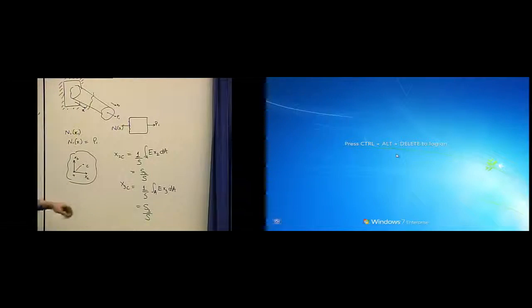But that is valid only at the centroid, so the centroid is evaluated in this manner. So that's how you find the coordinate of x2 centroid? Yes, because x2 and x3 are the cross-sectional coordinates. So the cross-sectional coordinates for the centroid, x2C and x3C, are defined in this way. It is essentially a sectional average of the stiffness measures. And of course, if I didn't mention, S is equal to the integration of E dA.